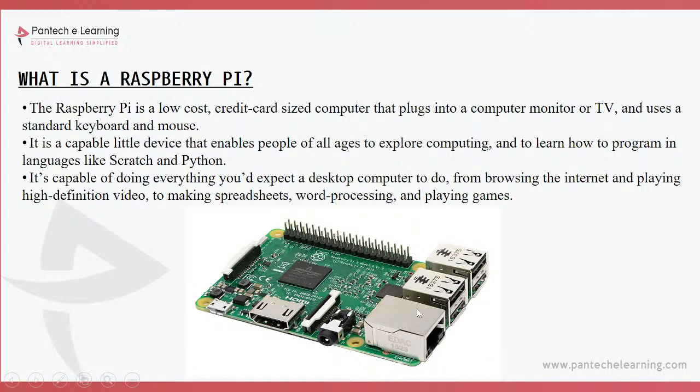Here we have to connect the LAN, this is the port placed for LAN purpose. If you connect the LAN cable, the internet cable, to our systems and laptops, then through VNC we can open it on our laptop or phone and access the Raspberry Pi. VNC Viewer has to be installed on the Raspberry Pi and on our phone or system. When it is installed, if you give power and internet, we can use it.